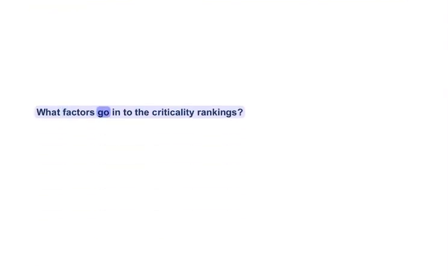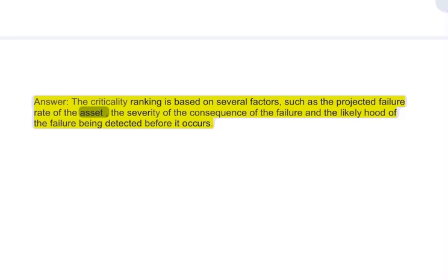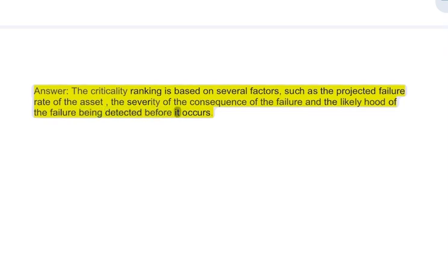What factors go into the criticality rankings? Answer: the criticality ranking is based on several factors, such as the projected failure rate of the asset, the severity of the consequence of the failure, and the likelihood of the failure being detected before it occurs.